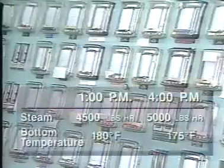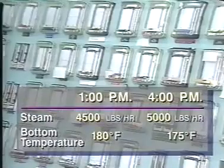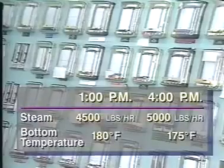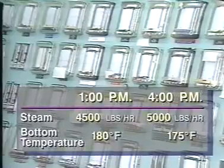The data should fit together. If the total picture of the operating conditions seems unreasonable, you should question whether the data shows the actual state of tower conditions. Suppose instrument readings tell you that the flow of steam to the reboiler has increased and that the temperature at the bottom of the column has decreased. Other tower variables remain the same. Does this data fit together? If you answered no, you are correct.